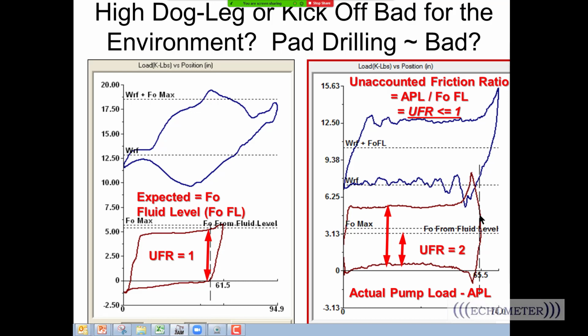And the operator said, "Yeah, this happens all the time on these wells." The only way to make it stop was to remove the friction. They tried rod guides, then they tried co-rod, and then they tried polyliner. He said once they do polyliner with co-rod, the noise stops. The roar leaves and the horn goes away. But I don't have any data to show that, just the word from the operator when we were at this well.